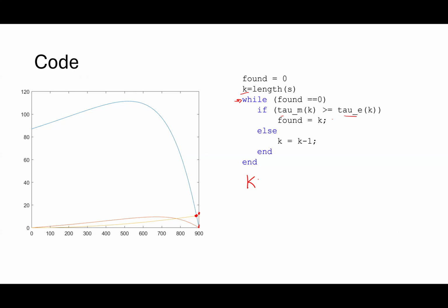So when you solve this problem, you're going to have a vector for your I1 and your I2 and your RPM and your torques and everything like that. It's going to tell you the index of the vector where the intersection occurs. So if I have an S vector, when this loop is done, S of k is equal to my operating point of slip. That's the point where that crossover happened. It's telling me the index where that crossover occurred. When I did that here, what I found out was that my operating slip was 1.45%.